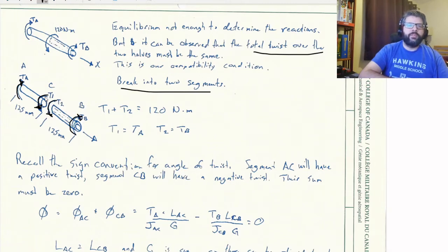So we know that basically T1 and T2, that's combined, some portion of the point load is going to go this way, and some portion is going to go this way. Is kind of the way it's going to work. But those two things combined needs to be equal to the original load.